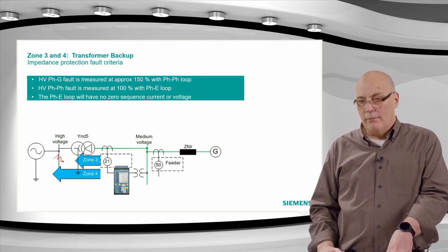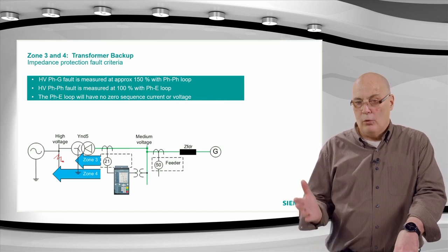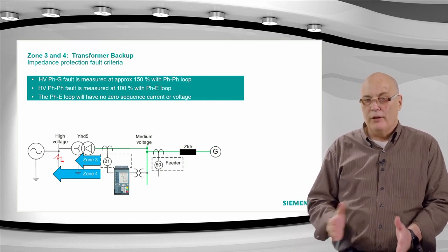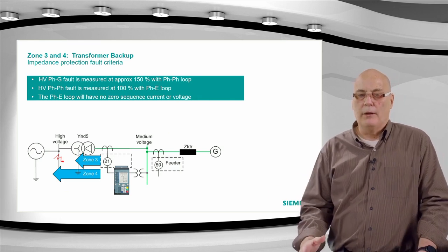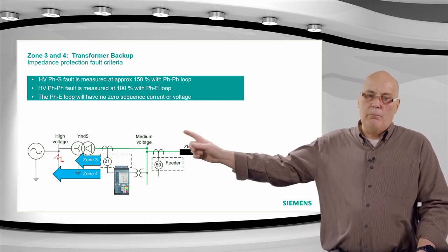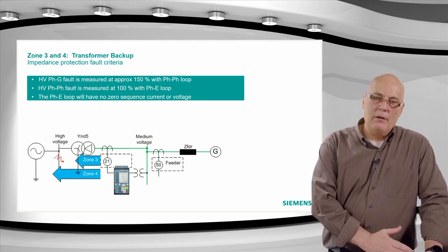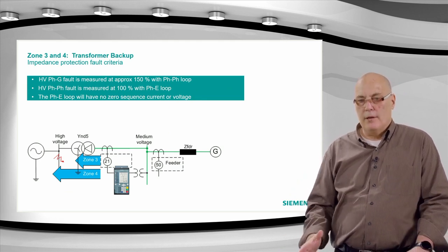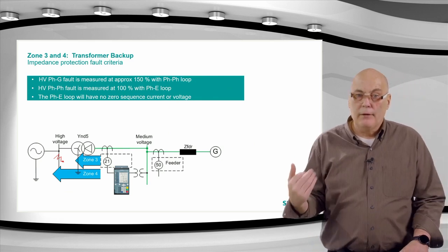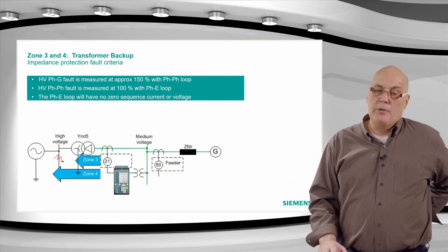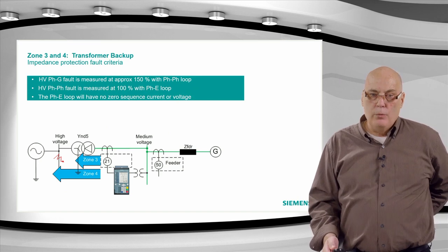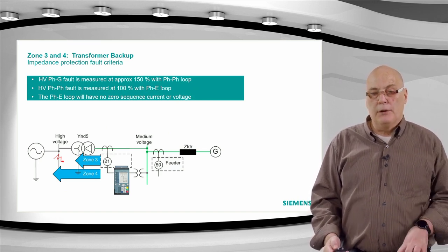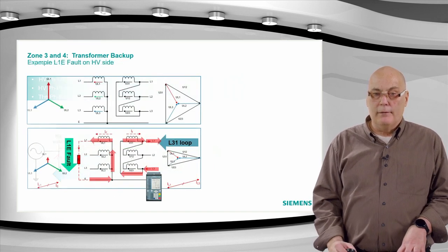If there's a delta in that, like you would have in an auto transformer, the delta would also shunt the zero sequence to a large degree. The zero sequence would not come through that transformer at all. So we typically will see on power transformers that if you have a ground fault on the one side, the zero sequence will not be coupled through to the other side. And remember in our loop selection, that was an important requirement: a single phase loop can pick up only if we have a ground fault detection, for example. So normal distance protection is not always going to be ideal over here.